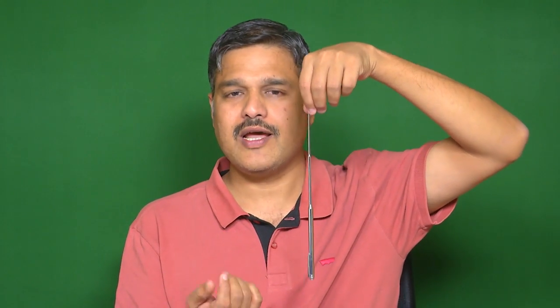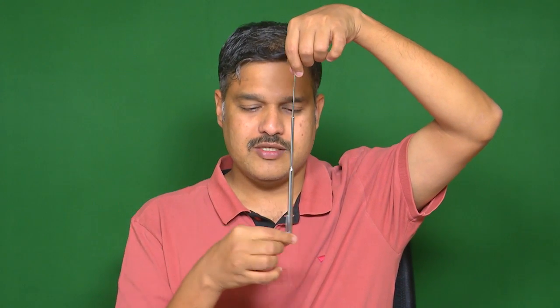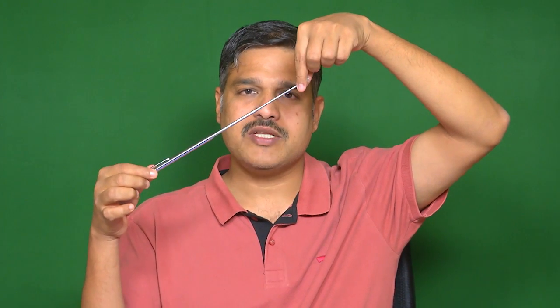And then what is over critical damping? If I leave it here, it will come to rest, but it will take much longer time to come to rest. One best application of over critical damping is recoil mechanisms in guns or automatic door closures. Usually when you open the door while entering and then leave it, the door closes slowly. If under critical damping were there in that door closure, it would come and hit the person before they enter. That is why that damping is adjusted such that it comes slowly and then shuts finally. So, that is over critical damping.